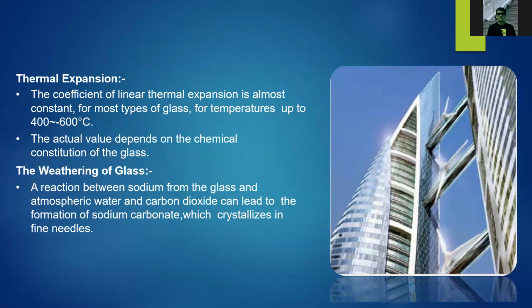The weathering of glass, a reaction between sodium from the glass and atmospheric water and carbon dioxide, can lead to the formation of sodium carbonate, which crystallizes in fine needles. There is what you call glass discoloration if it is exposed to carbon dioxide, pollution, other harsh chemicals or salty waters. So there will be discoloration, and sometimes the glass will be eaten up by the environment.